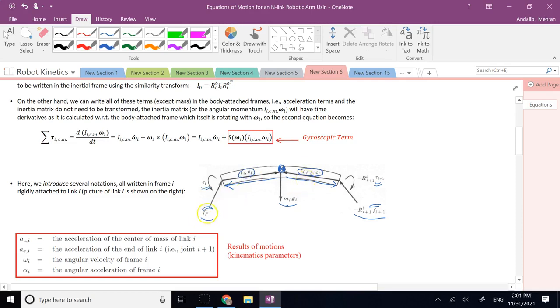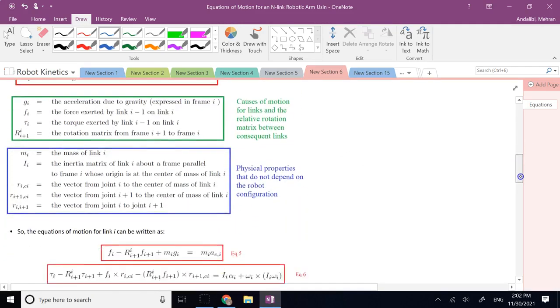So if I want, let's say, the moment of Fi about the centroid, it's going to be this vector, which is really negative of Ri and Ci. That's this position vector here. And then cross multiplied by Fi. And a similar thing for this one. And as you know, if you change the order of a cross product, the negative sign goes away. So you can also write it as Fi cross Ri and Ci. And that's what you see here down in the equations of motion.